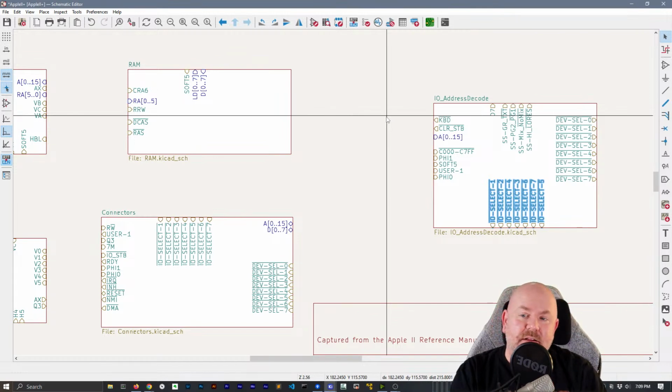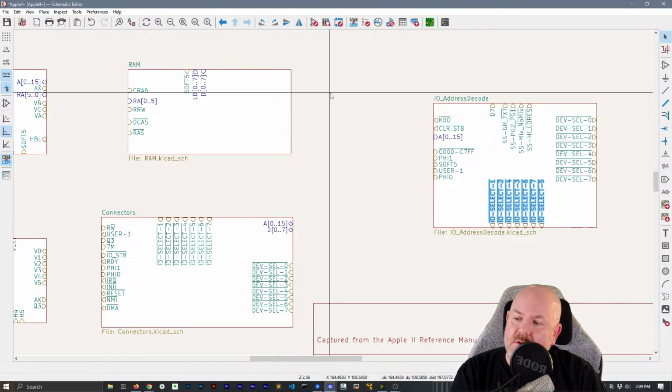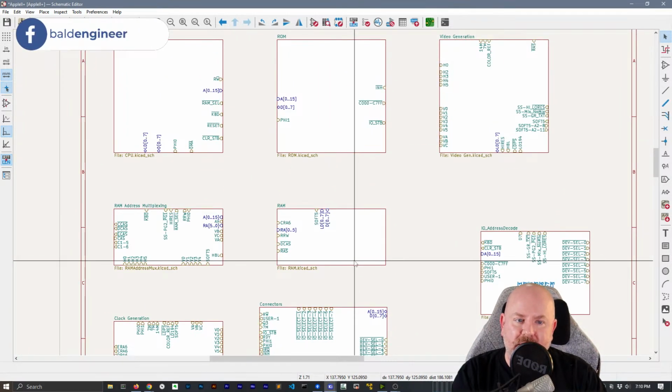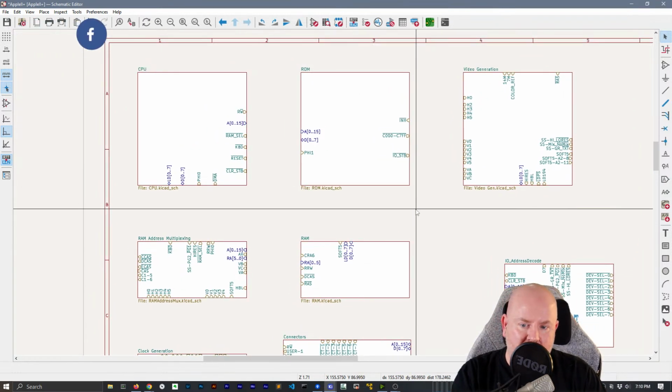Sam, I have no idea. But the packaging should have the land pattern, and then a recommended land pattern, and then add a buffer on each side, like 6 mils on each side to whatever the land pattern is. Then you can literally calculate the maximum you can fit. I'm picking 6 mils because most board houses are around 6 mils for copper to copper.